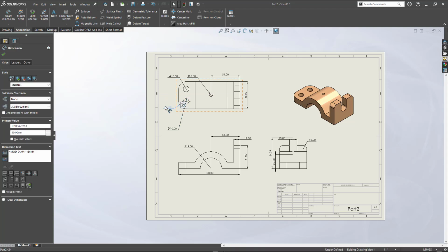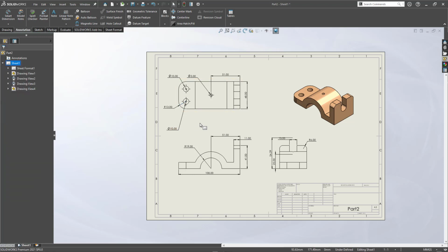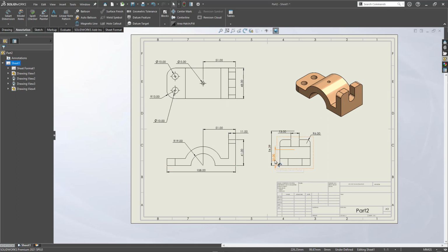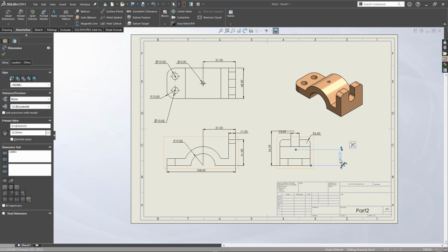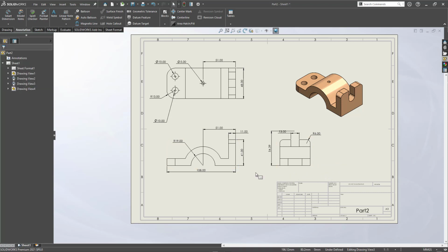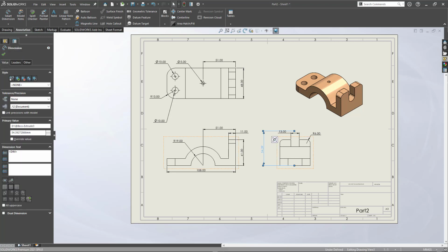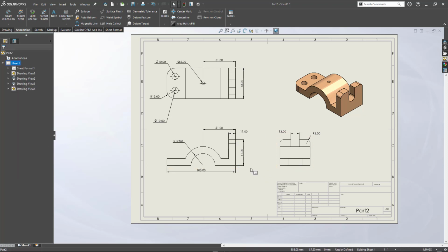It should be here. This is the fillet angle. If you want to add extra dimensions, you can even do that. So this 25 is not needed. If you want, you can keep it. I like to delete it, unnecessary dimensions. So here this also I don't want it. Yeah, and now I would like to have this dimension here.